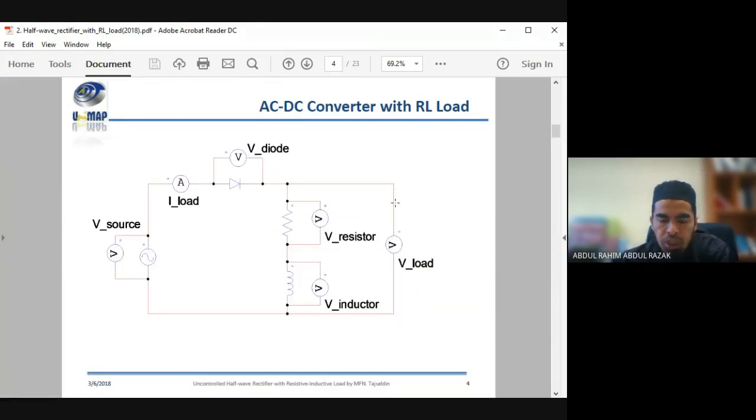In terms of voltage, usually we proceed in lab to expose you all to the real situation of a real world circuit. You have to bear in mind, when you want to measure voltage, the measurement is taken by putting your probe across the terminals of the device.